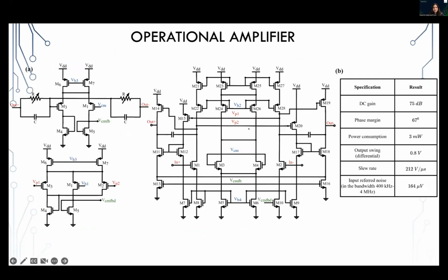Going a little inside, each of these operational amplifiers I showed, these rectangles, are made of transistors. This is one of the main differences between analog and digital ICs. In digital IC design, microcontrollers and microprocessors are based on logic gates, AND gates, NOR gates. There are transistors inside the gates, but we focus on logic gate based design in digital ICs. But in analog ICs, we directly work with transistor level designs. This is a transistor design of the operational amplifier I showed. It has around 50 transistors. And this op-amp has a gain bandwidth product, or unity gain frequency, of 600 megahertz.